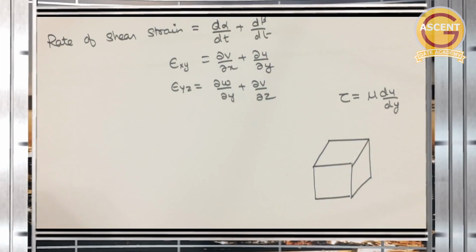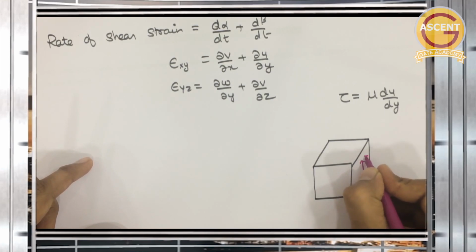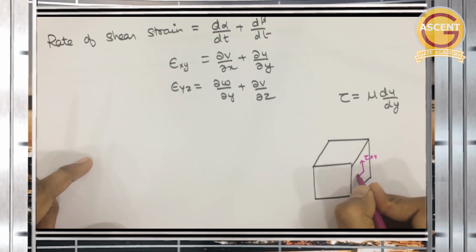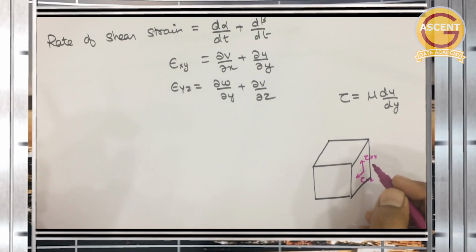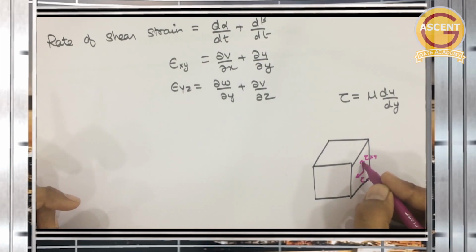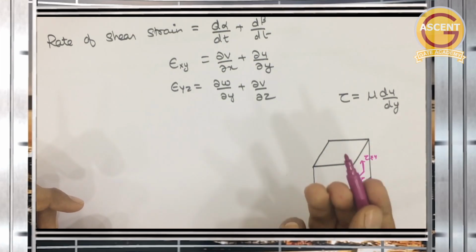Okay, here shear stresses will act. Here it will be tau xy, tau xz. Okay, how to denote this I have already told you in the strength of materials lectures, if you have watched them. If I am drawing this, the first subscript x represents the perpendicular direction. So perpendicular to this plane is the x-axis, so this will be x, and the second subscript represents the direction in the same plane in which we are indicating the arrow.